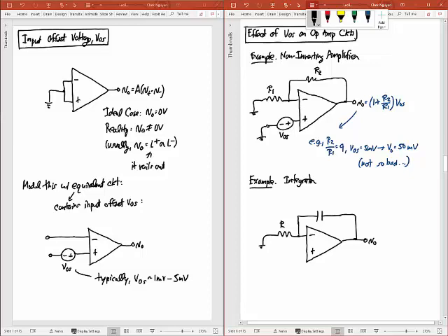All right, so this is my capacitor C, and at my positive terminal, I want to put 0 volts again. But, of course, since this is an amplifier that has an offset voltage VOS, putting 0 volts really means grounding this terminal.